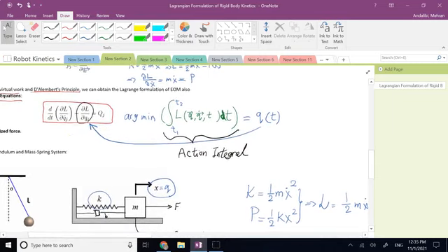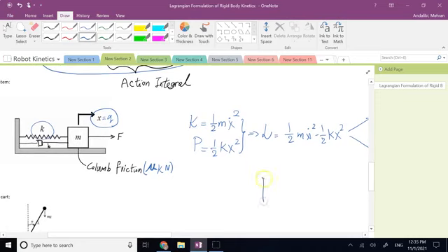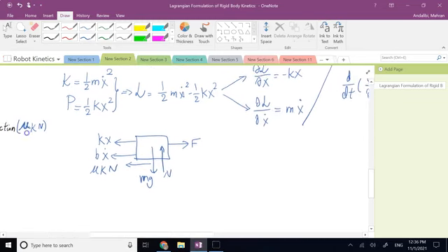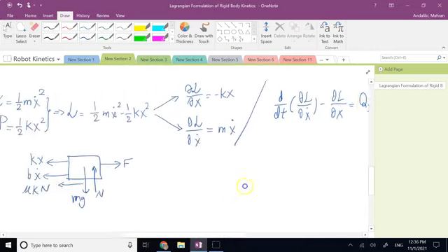And if you look at this system here, if you look at this block with mass m, clearly at any point there are several forces acting on it. There is the external force F, there is the spring force kx, which we included already. There is Bx dot, which is the damper force. There is the Coulombic friction, which is mu k times N. And there is N and mg. mg is not doing anything, N is normal to the direction of motion, has no work. So now from this FBD, free body diagram, we have to come up with what this Q of x is.